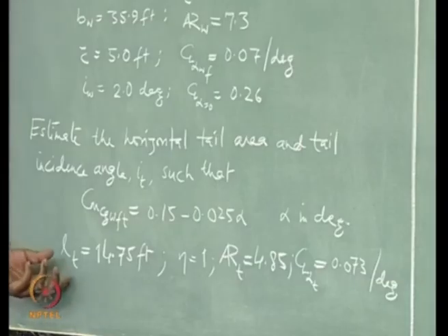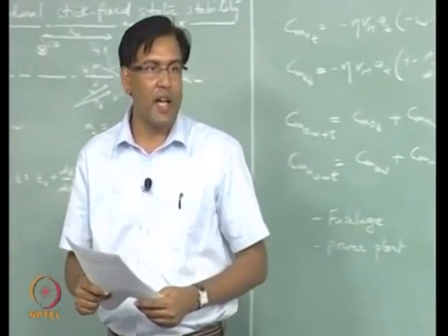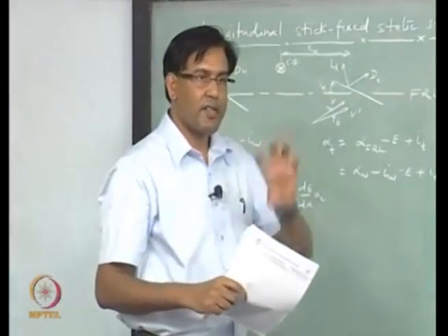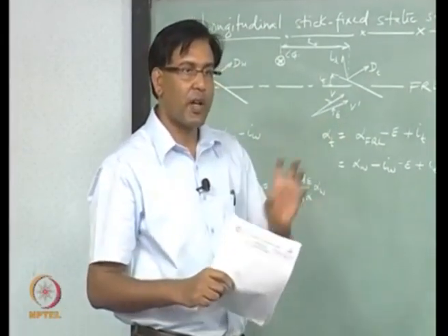How do you decide on LT? Now LT will depend upon a lot of things, right. First of all, the tail has to produce enough moment, right, to trim the aircraft.